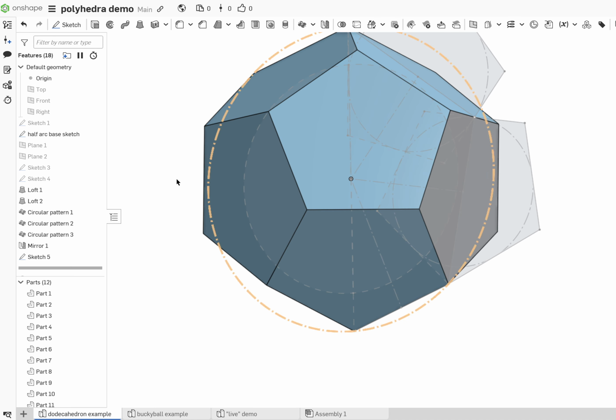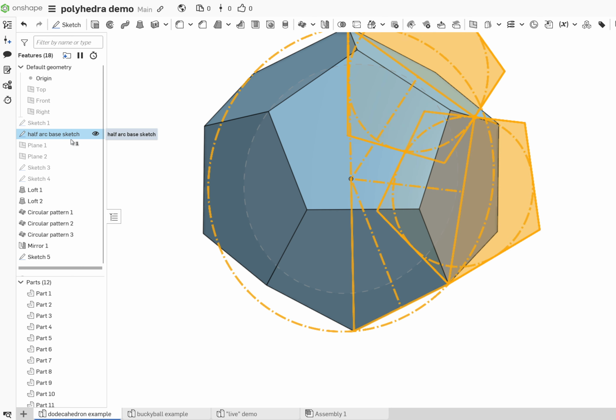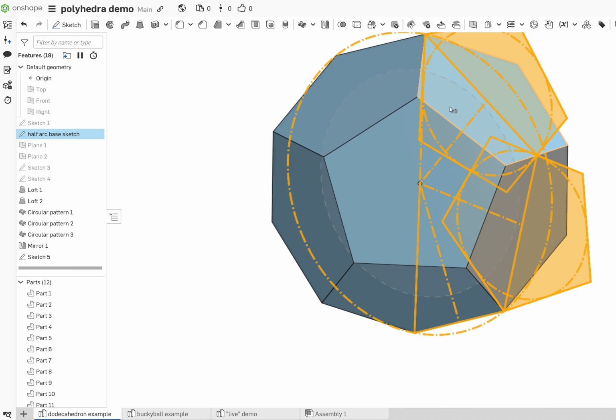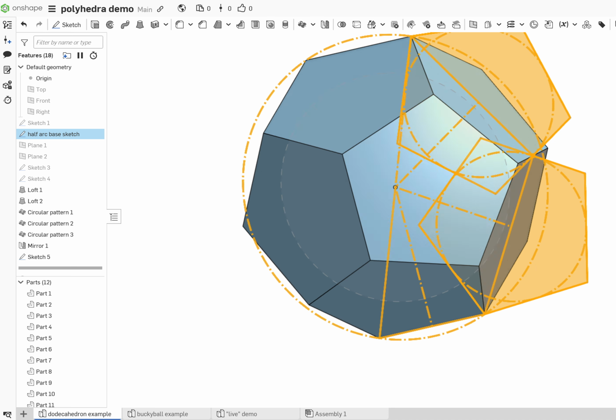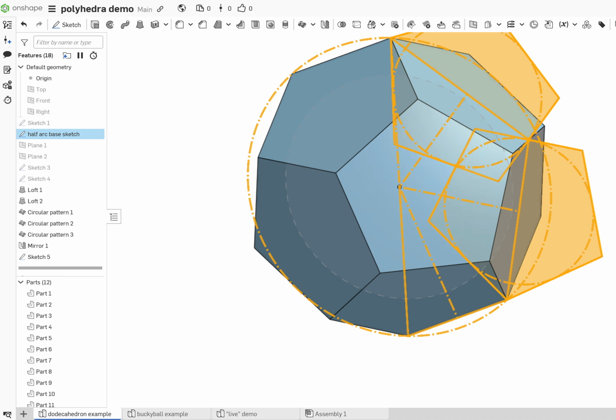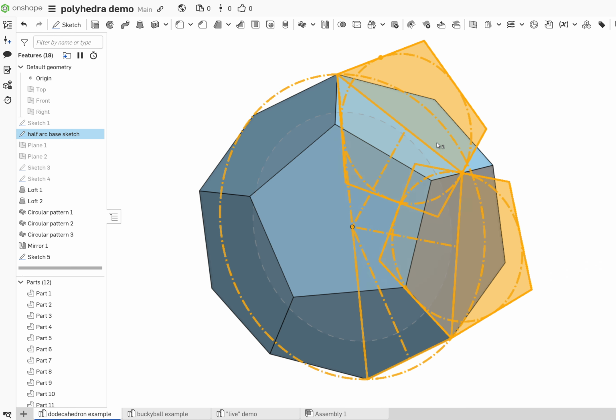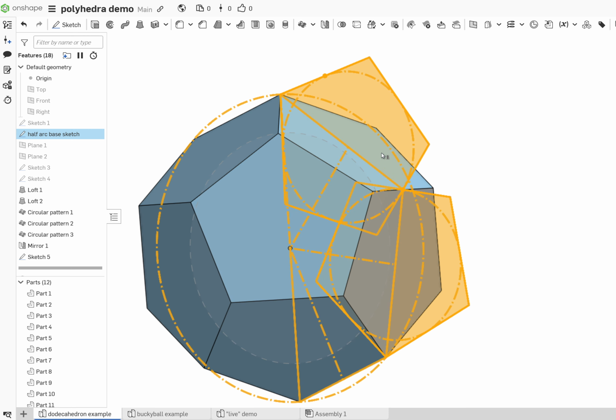And that arc segment looks like this, where we've taken those planes and rotated them in plane with the sketch plane, with the initial slice. You can do this with revolves, but this just does that step in your head and works out really well.